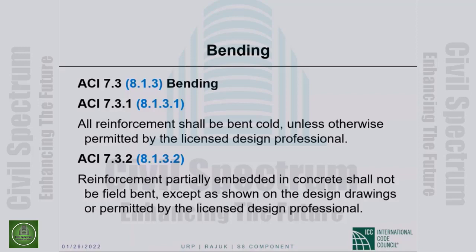Reinforcement partially embedded in concrete shall not be field bent. This is a very serious restriction. Shall not be field bent, except as shown on the design drawings and permitted by the licensed design professional. It has to be shown on the drawings or permitted, not and. Or if it is not on the drawing, it will have to be permitted by the licensed design professional. Field bending of embedded bars.